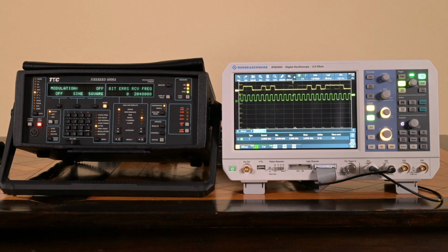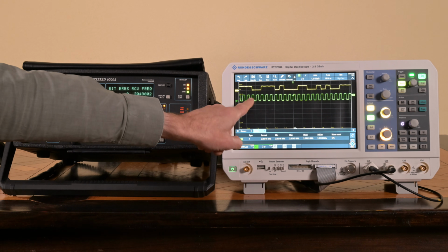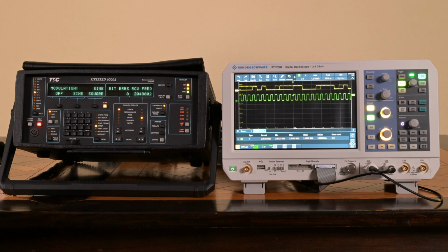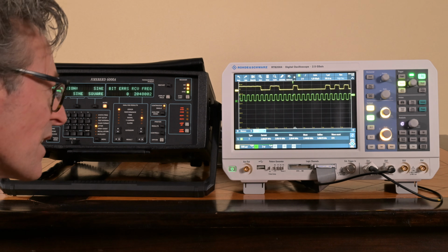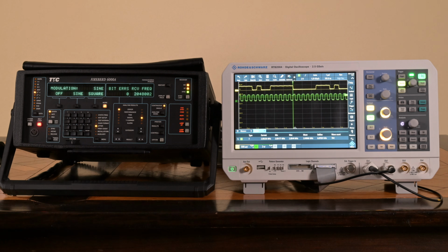The clock is not super stable. This is not a reference rubidium clock or something like that, but we're happy with it, and it's a fairly constant clock here. Now we're going to add some jitter to the equation. So I'm going to have sine modulation here, and what we can already see is that the clock is starting to show some issues, also in the standard deviation, which is already running into kilohertz. So clearly there is significant jitter going on, but apparently we have no bit errors yet.